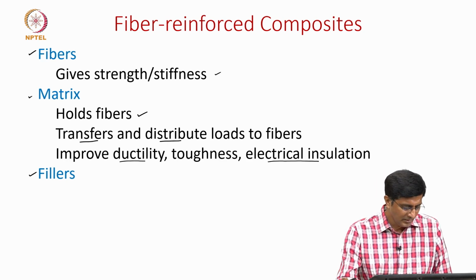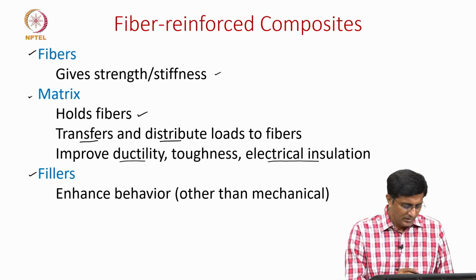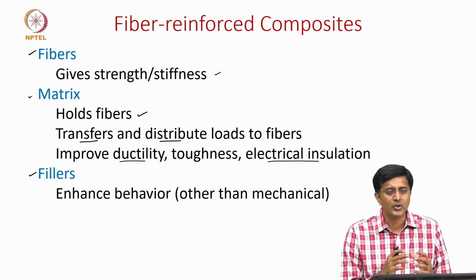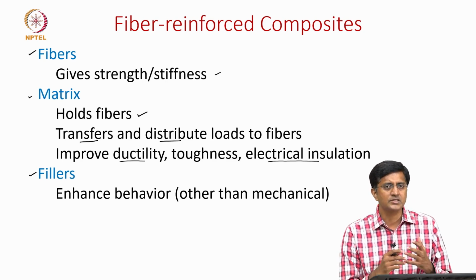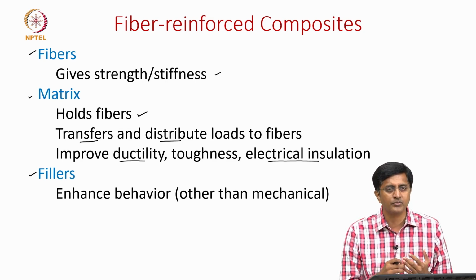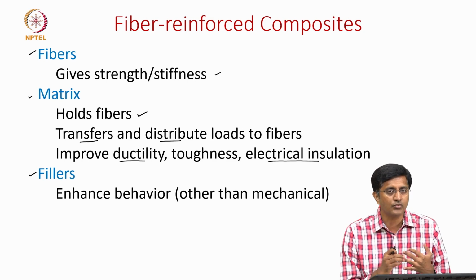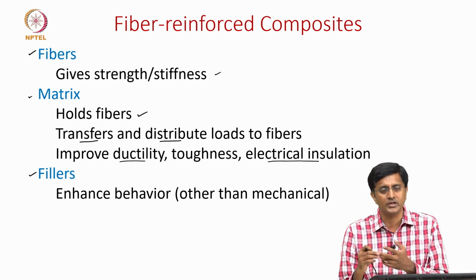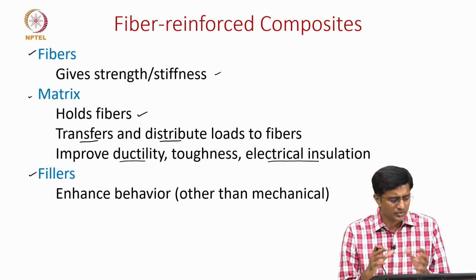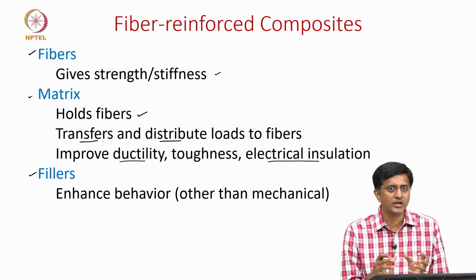And lastly, regarding the fillers, they are not used to enhance any of the structural properties of the materials, but there are other properties which they can take care of, such as how do we reduce the weight of a composite, or how do we ensure that this composite does not degrade when exposed to UV or when it is close to fire. There are many other filler materials, we will come back to that in greater detail later.